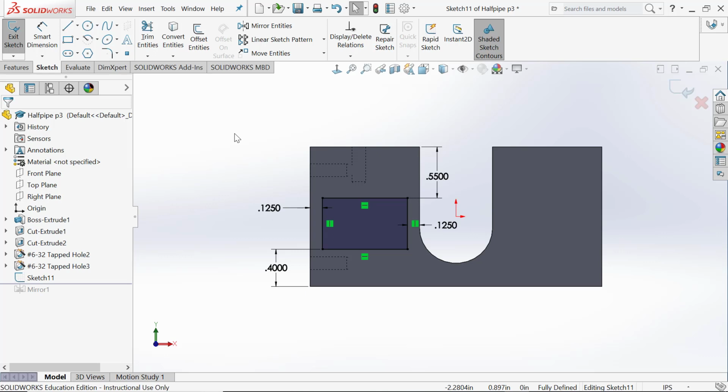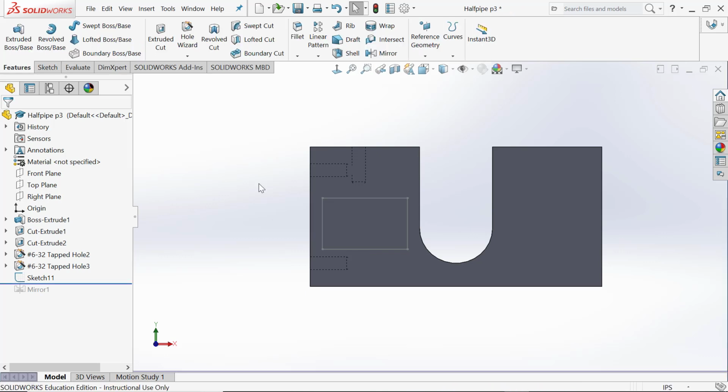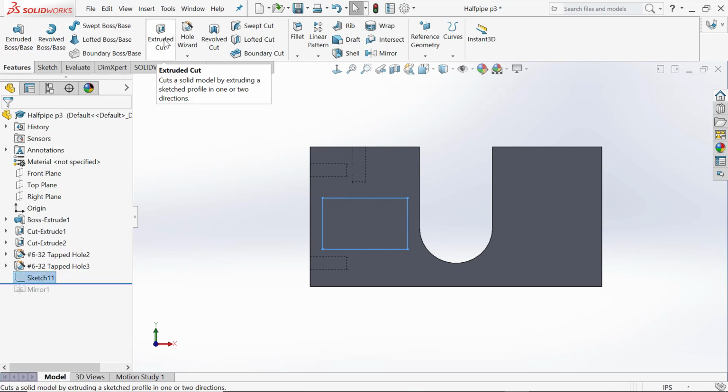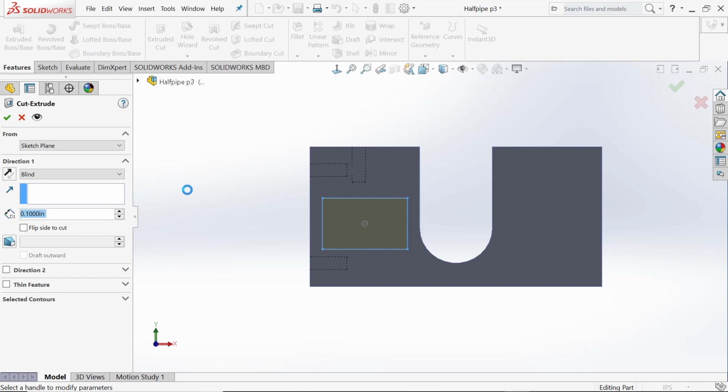Yeah. Everybody's good. Awesome. So we can exit this sketch, not with the red X, of course, because you don't want to lose our work, but with the blue thing. And now we want to select that sketch over in our design tree and choose extruded cut. Now, important you pay attention right now and not be talking, because we're going to do the offset from surface thing.